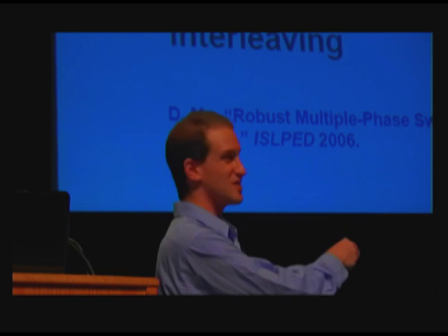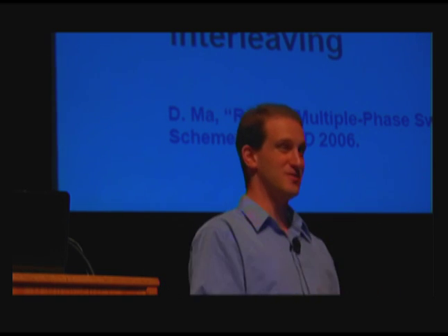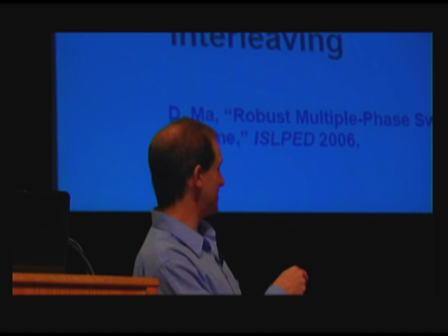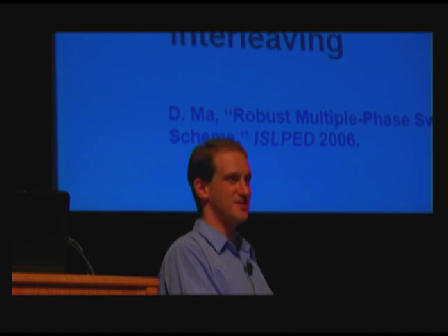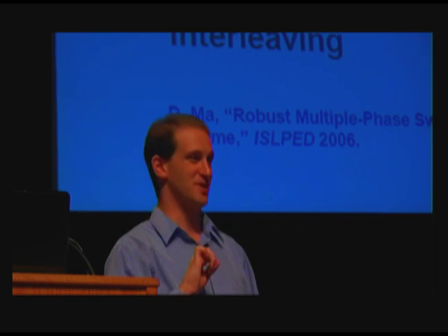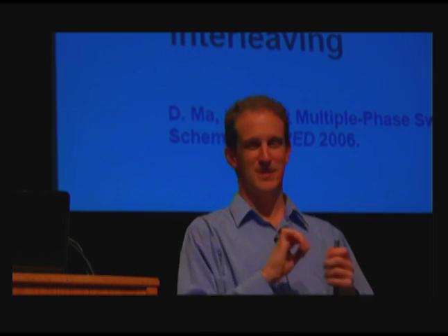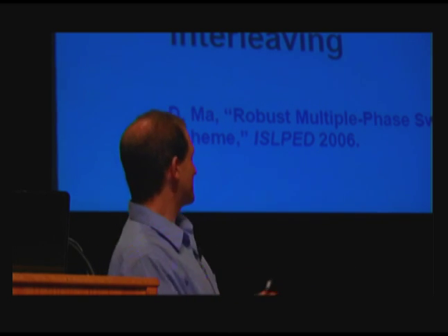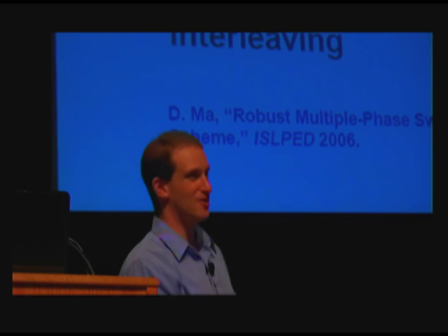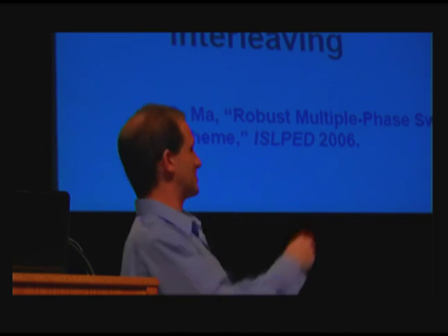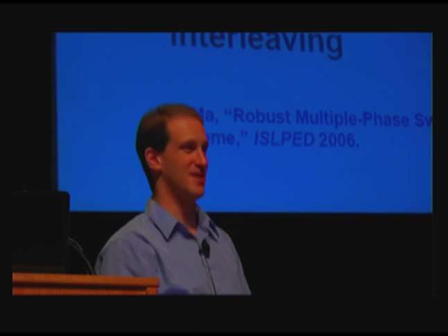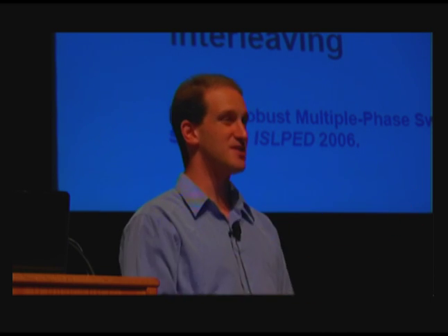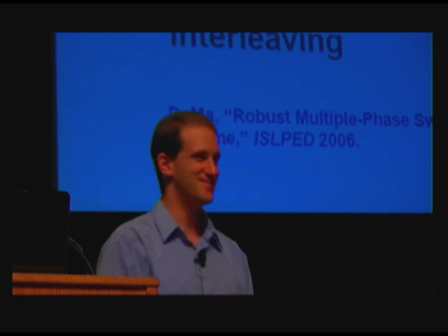Okay, now, there is some resistance from the switches and things like that, so there's a little bit of a loss there. But you can immediately see that in this example, half of my capacitance is exactly just like a decap would have been. Okay? So to be totally accurate, this cap that's between V in and V out is not exactly like a decap because there's some series inductance and et cetera in that input supply. But basically the equivalence holds to within essentially a factor of 2. And you can argue about is it exactly a factor of 2 or somewhere around there, but basically it holds to within a factor of 2. Thanks.